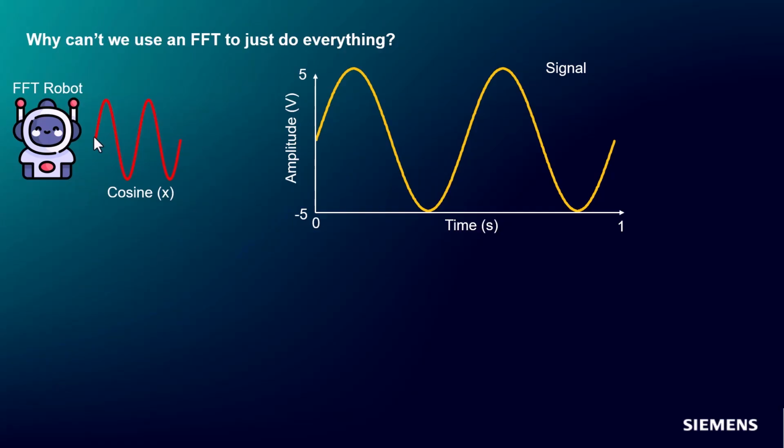And the way he does that is he takes a cosine wave or a sine wave, something very specifically that looks like this shape, and he probes the signal with different cosines and sine waves, and then he's going to find out which ones have the highest correlation. And I challenge you to not think of the FFT just as a spectrum of the frequency content of a signal, but the correlation or the confidence of the frequencies of the signal. And I'll explain what I mean.